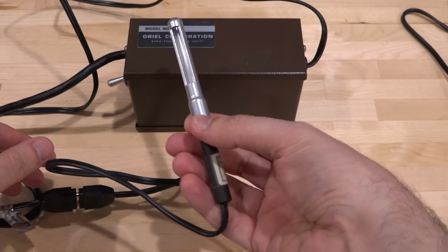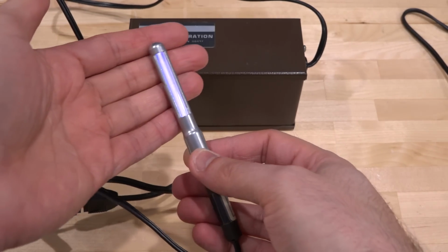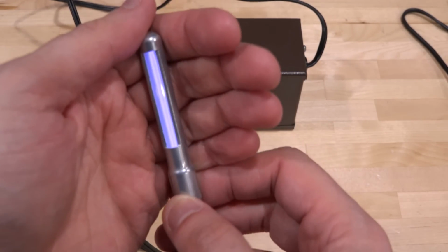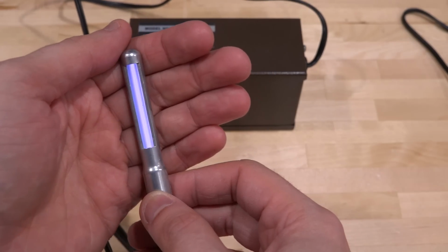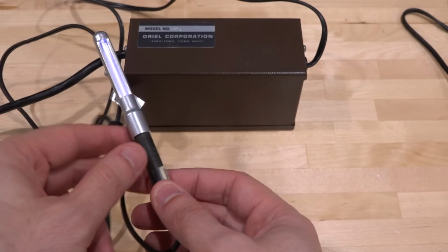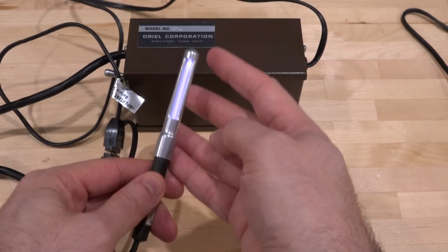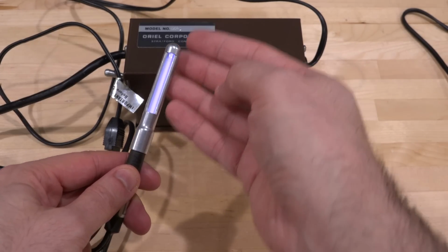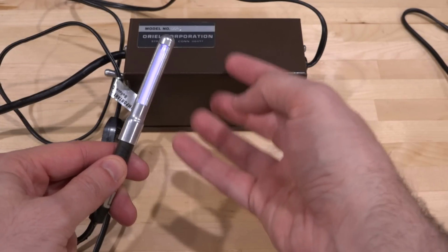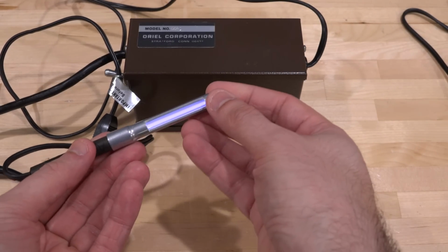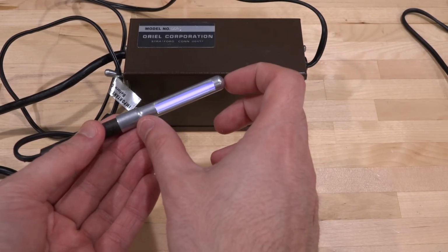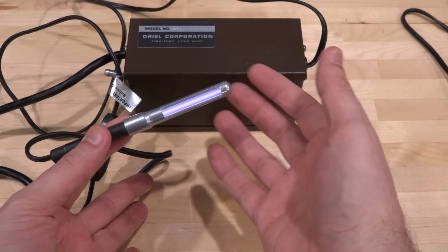Let's try a different one. And this one is argon. You can see a little bit of purple pink color to it. Looks quite nice actually. And the reason these are difficult to drive is because you would need a very high voltage to strike this tube, so to begin the flow of electrons and create these photons that come out of it. But then once that ionization happens, the resistance of the tube drops drastically by orders of magnitude.